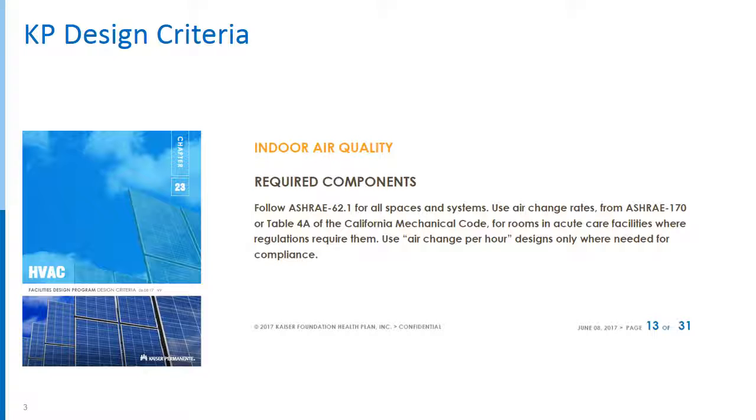So KP has and owns MOBs that were designed using air changes. They're pretty easy to spot, at least for me. You just look at the energy bills and you look for the ones with double the energy, and boom, there they are. And so when we overhauled the standards in 2012, we made this very explicit. We say do not use air changes unless you really need to, like by law. And that's what it says now. So the 2017 version of KP standards is the same as 2012. Don't use air change method unless you actually need to.